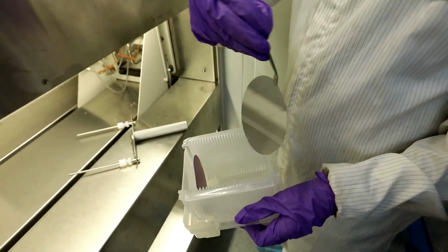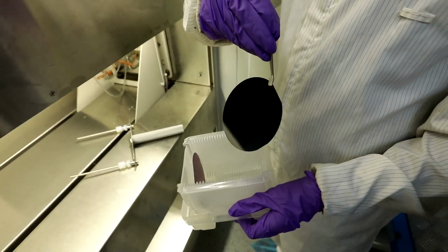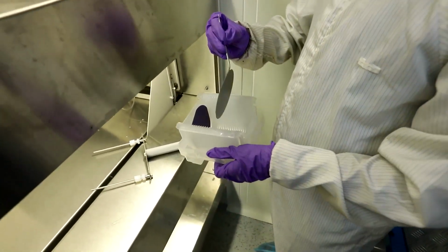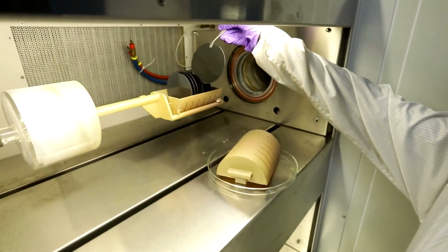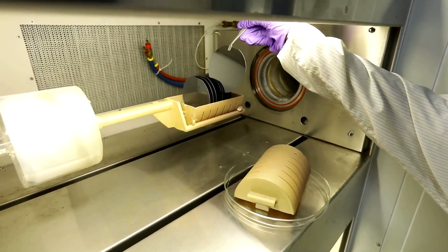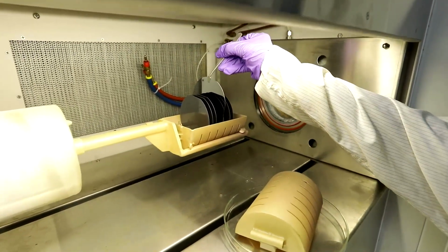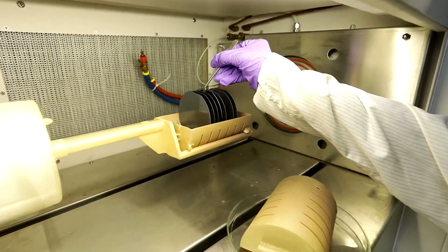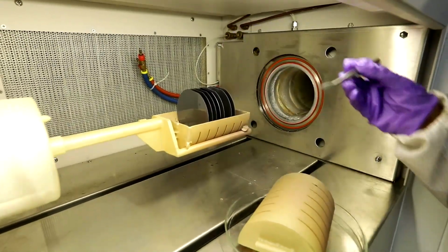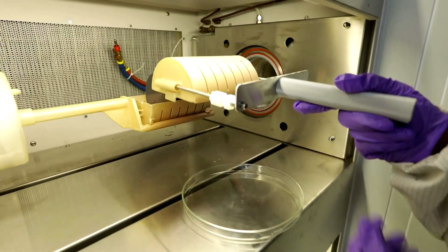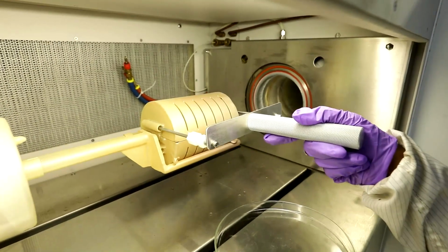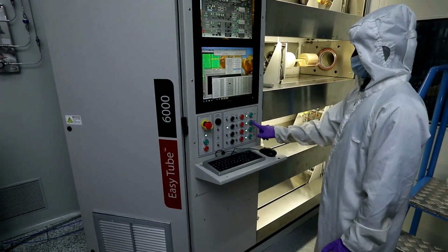Note that we should load our sample silicon wafer for oxidation immediately after the RCA cleaning. RCA cleaning video will be available on our website. The cleaned silicon wafer, 4-inch, is placed in between the dummy silicon wafers to maintain uniform flow of gases, resulting in uniform growth. Actual process. After loading the wafers, we close the chamber and start the reset program.